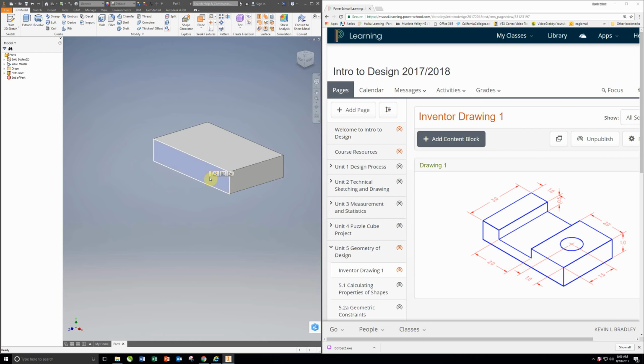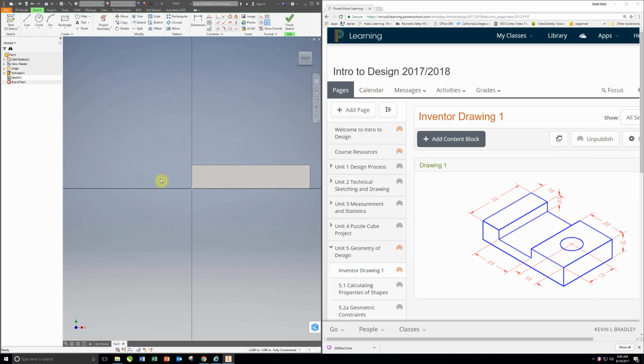So I'm going to go ahead and click on this front face, and I'm going to put a new sketch on that face. So this guy right here is actually edit sketch. I'm going to create a sketch on that face. A lot of times I don't use these buttons here. I use this up here. So I'm going to start a sketch on that face. So again, select the face, click on start 2D sketch, and now we're making a sketch on this face.